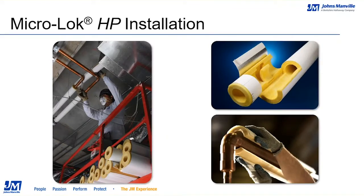The scrim lines also match the scrim pattern on butt strips, which is a tape used to join 2 pieces of pipe insulation sections together. This provides a more seamless and aesthetically pleasing match at the joints. JM provides butt strips with every carton of pipe insulation. Microlock HP and HP Ultra also come with a self-sealing lap, or SSL, adhesive already installed on the jacket to make the sections easy to seal.